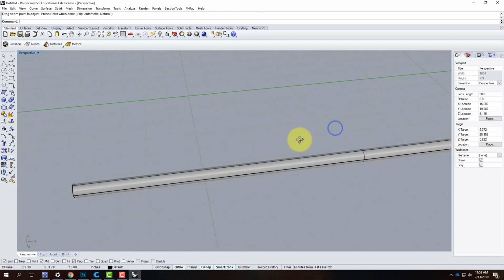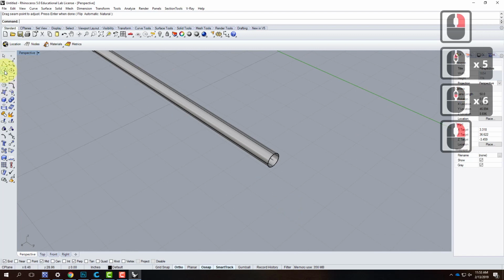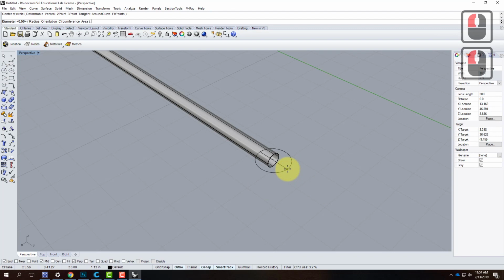So it's time then to switch to the donut on the end here. And so the donut has a couple circles involved. First circle, the diameter is only 3/8 of an inch, so it's smaller. So that is 3, oops, helps if I type it correctly, 3 divided by 8 inches, or 3/8 inches, or 0.375, is that what it is? 0.375 if you wanted to do it mathematically. I'll go ahead and press enter. And there's the inside.